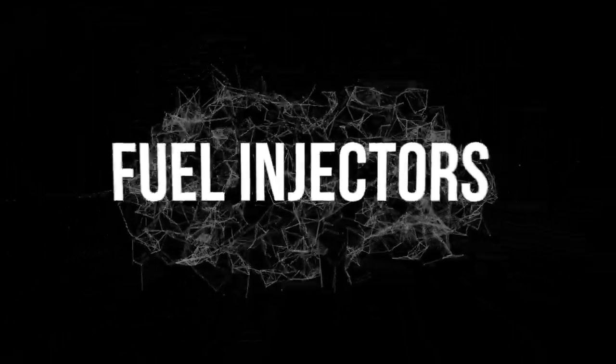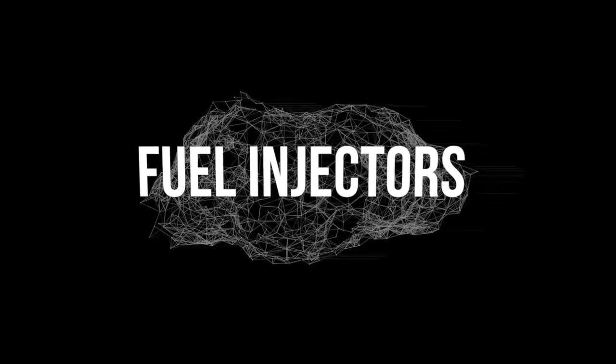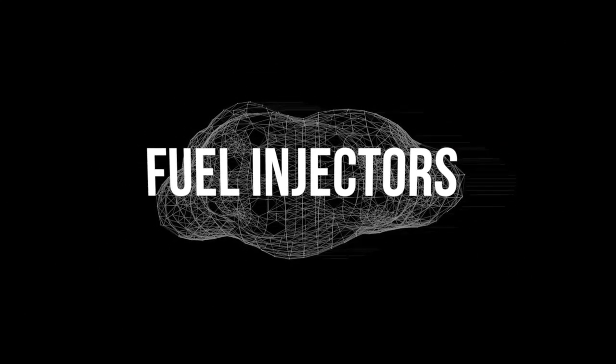Now that the engine management system's got a whole bunch of information from the sensors, it can start making decisions about controlling the fuel injectors and the ignition system. Fuel injectors come in a range of different shapes and physical sizes, as well as different flow rates and spray patterns. They also have different solenoid resistance values and opening or injector dead times.